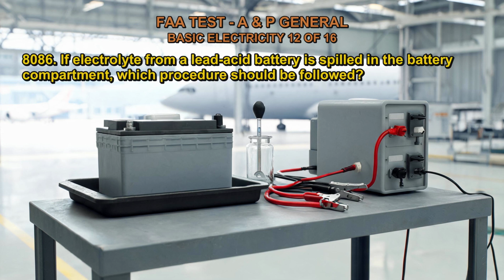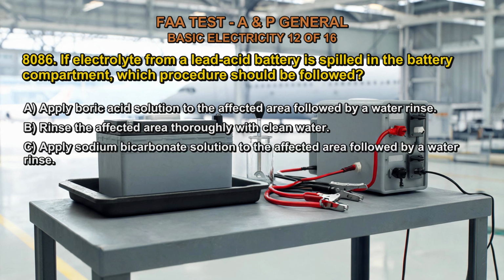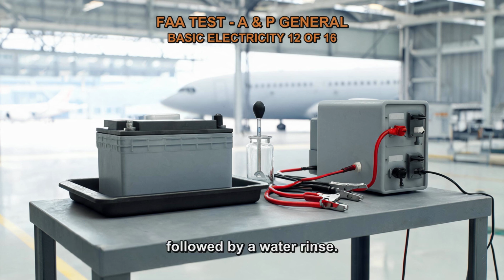Q8086. If electrolyte from a lead-acid battery is spilled in the battery compartment, which procedure should be followed? A. Apply boric acid solution to the affected area followed by a water rinse. B. Rinse the affected area thoroughly with clean water. C. Apply sodium bicarbonate solution to the affected area followed by a water rinse. The correct answer is C. Apply sodium bicarbonate solution to the affected area followed by a water rinse.